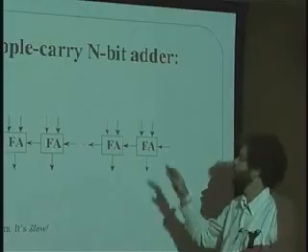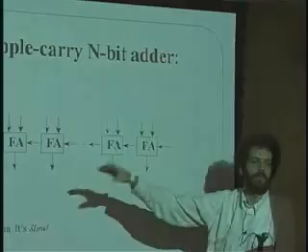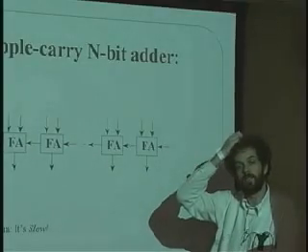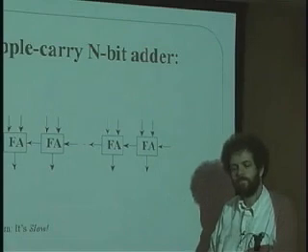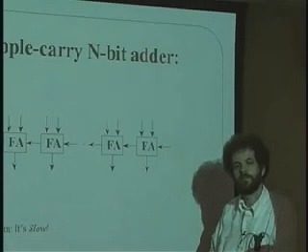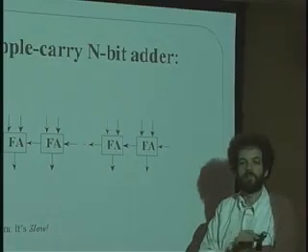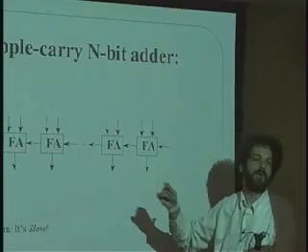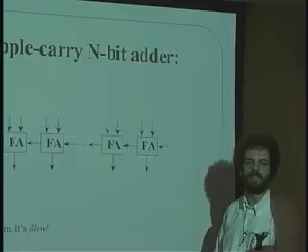Absolutely right. And in fact, if you add 1 plus 1 and just get 2, you're only going to use these 2, and the rest of them are going to be able to come up with the right answer very, very fast. You can have a 32-bit number or 31-bit number, and still somewhere along the line you can start the 4th adder without having gotten the results from the 3rd adder. That is also true, and we're going to talk about just one of the many ways that you can do that. In fact, that's sort of the later part of the lecture here.